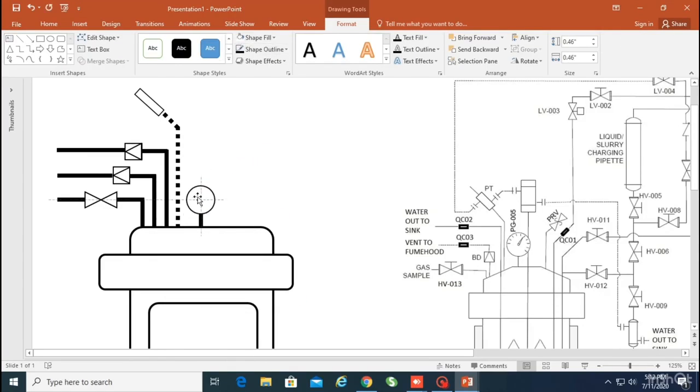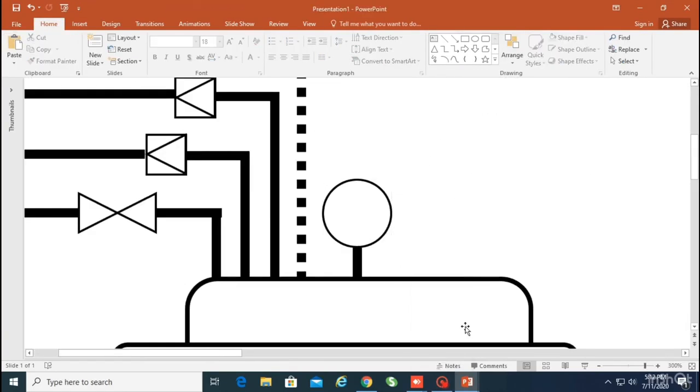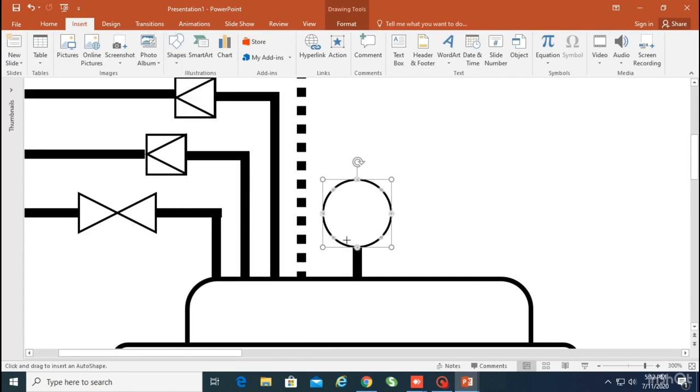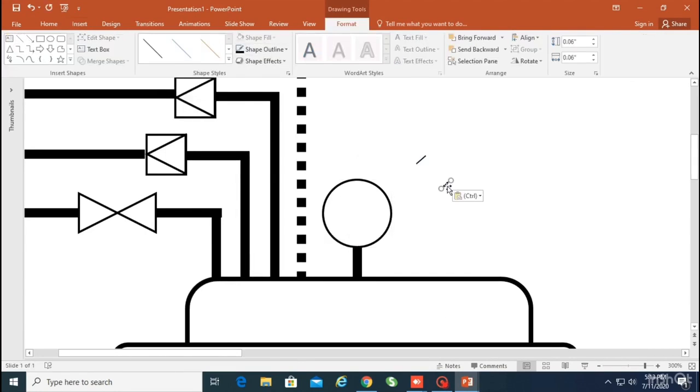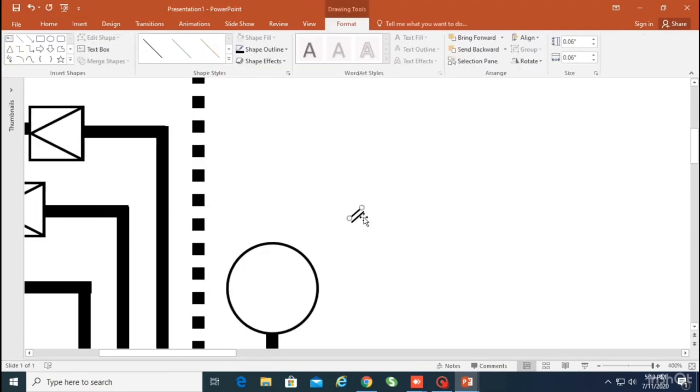What you have to do is take a small circle, then zoom in a little bit and take small lines. To draw the numbering of the gauge, you can use small lines, group them together, and place them one by one. It's difficult to make them in a circle, so I found an easy way: make them two in a group, and then copy them with a little bit of distance. You can copy them by replacing them, and moving them from one point to another.